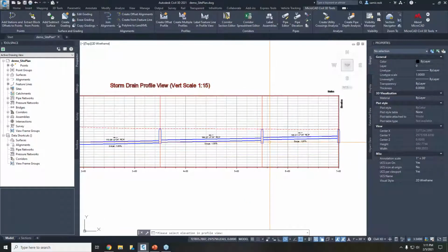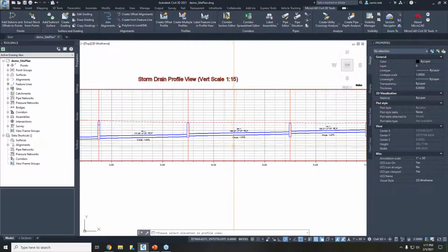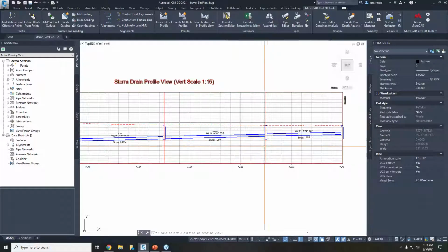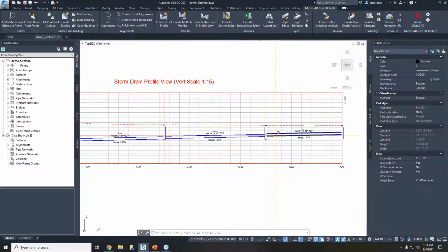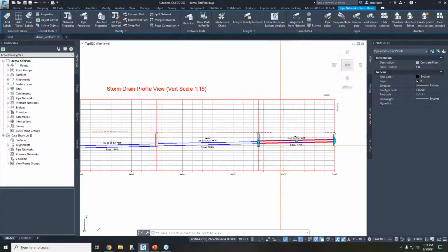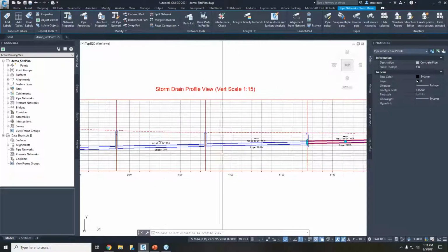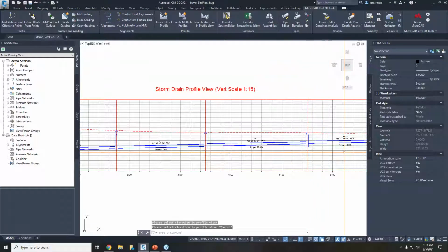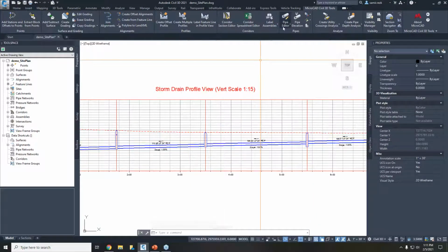Now, if you would do this in Civil 3D, it is definitely able to do it. The only problem is that you select one pipe at a time, go into pipe properties one at a time, and re-input the information for the pipe. And you'd have to do this 4 times. If we're thinking about it a little bit, maybe a minute per dialog box here, so 4 minutes just to design 4 pipes, and it's a time-consuming process for many people. And this needs one single place, a one-stop shop to redesign the pipe run. So really great.